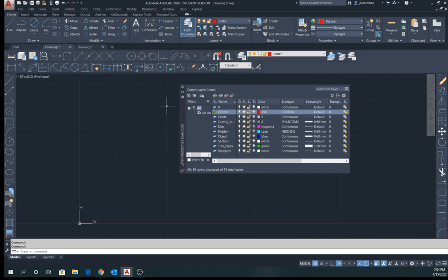Now, when you are done, you should close out the layer properties while selecting the construction layer. And there's actually two ways to select a layer. One is to just click on it, and the other is to actually click right here on this green stack of layers. So if I click here, you can see the selected layer changes. So I'm going to select the construction layer and then X out of this.